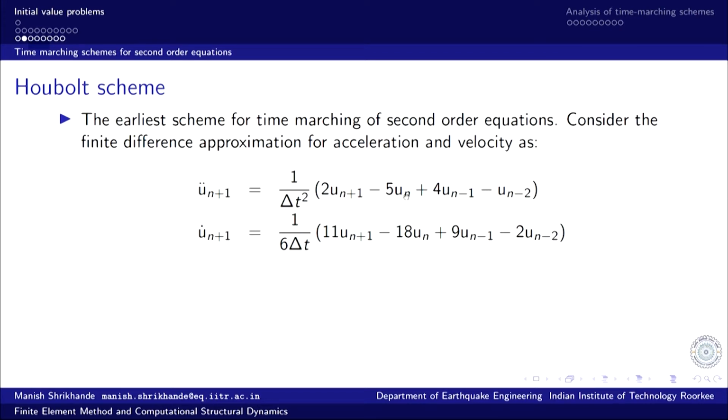So, all of these terms are displacement terms and the denominator is twice delta t squared, and here all of these are displacement terms and the denominator is delta t. So, it is a velocity term. And once we substitute these terms in the governing equilibrium equation, the only unknown would be u n plus 1. So, the entire system can be compressed and transformed into an equivalent stiffness matrix multiplied by the displacements at the n plus 1th time instant, and then the system can be solved as a quasi static problem at that particular time instant, linear simultaneous equations.